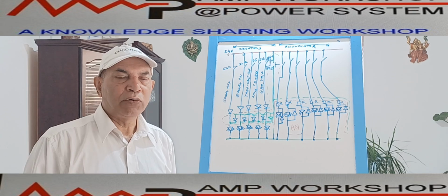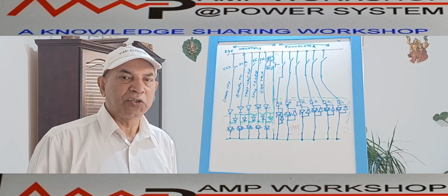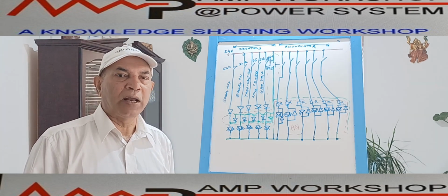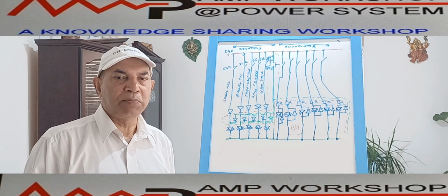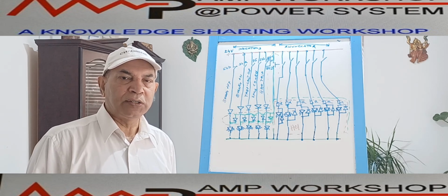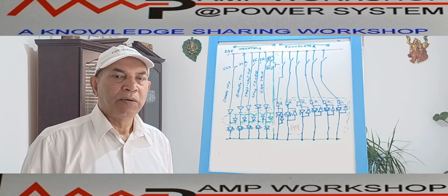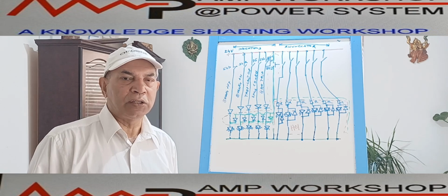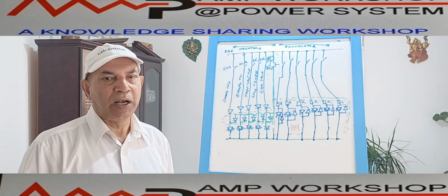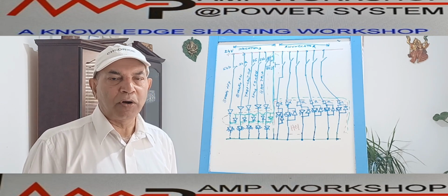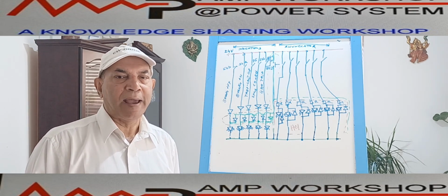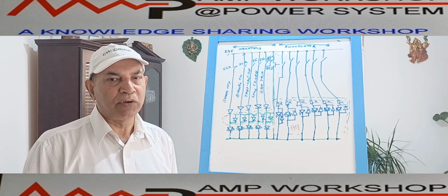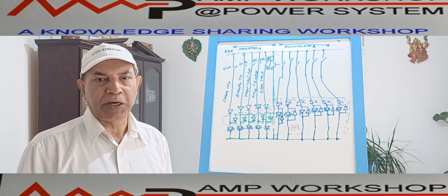In the old days, we used separate discrete circuits for the alarm and indication. The alarm system contains alarm as well as indications, but the healthy operation is monitored only by the indication lamps, while the abnormal operating condition is monitored by the annunciator system, which contains indication lamps as well as a horn or speaker.